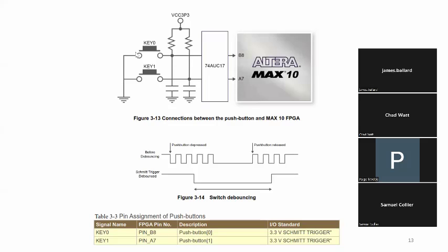Would you please tell me at this P0 position, open? Yes. Okay. B8 will be high or low? Low? Oh, wait a minute. Looks like it's going to be high. Why high? Because the source should be the VCC, I'm assuming. Yes, that's correct. That is VCC up here. So if you wanted to short it out, you would push key 0 down, I guess.